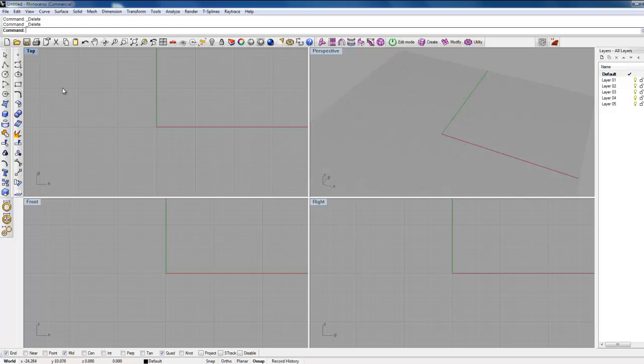So first of all we need to start off with a circle, which is a ring size, the size of your finger. So if we click on this icon here, it comes up with circle center radius. What we need to do is put that in this space. Now if you imagine this as a piece of paper, that's how I sort of do it at first anyway. Each of these squares represents a millimetre, and this represents the middle of the paper, the centre of the paper. If you can see that.